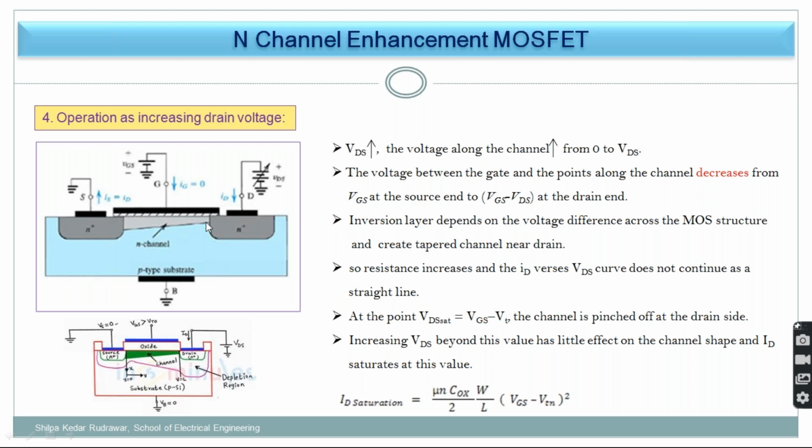As this is tapered, previously I had the full way to go, now it is just shortened, which means a bottleneck gets created over here. Electrons are there but crowded, and that's why resistance increases. As resistance increases, previously the current was increasing exponentially, now it is somewhat reduced.